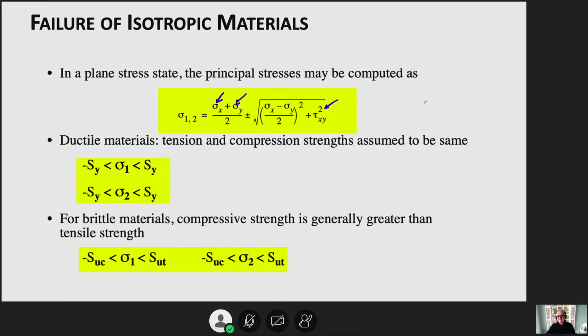Now, this is basically the Mohr circle approach, that given a state, you're going to be finding this, and tau max and tau min will be over here. So this is the tau axis, and this is the sigma axis. So this is the Mohr circle.